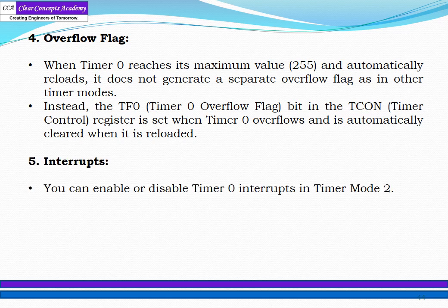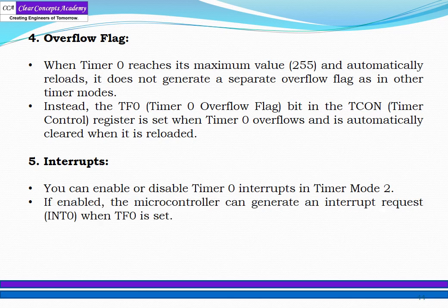Now interrupts. You can enable or disable the timer 0 interrupt in mode 2. If enabled, the timer can generate an interrupt request on INT0 when TF0 is set.